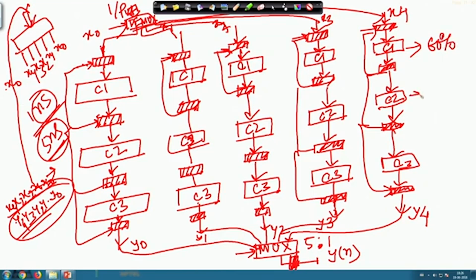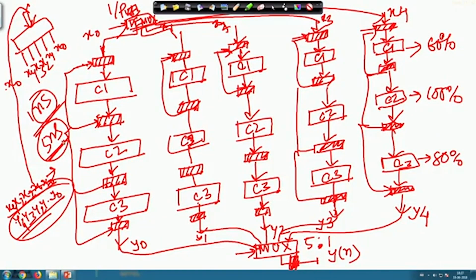This is 100%, that means at all times the clock frequency is 5. So, these blocks are running at 100% rate, but this is working at 80% rate. Why? Because these blocks are basically sitting idle for 1 nanosecond delay, where the clock period requirement is 5 nanosecond delay.